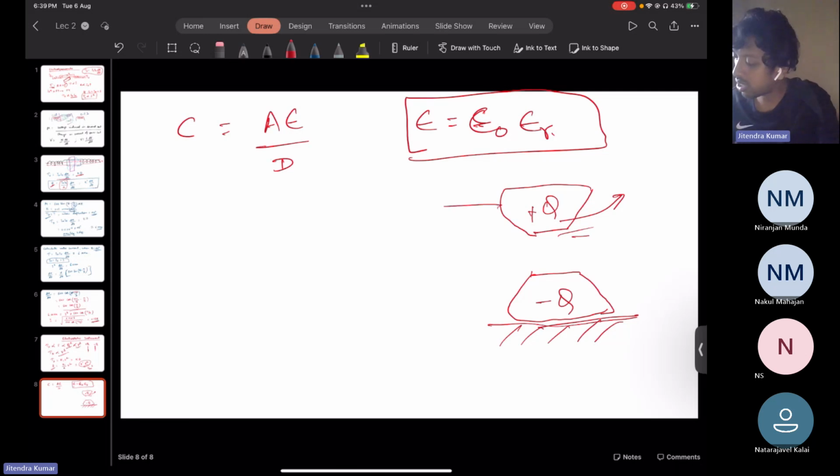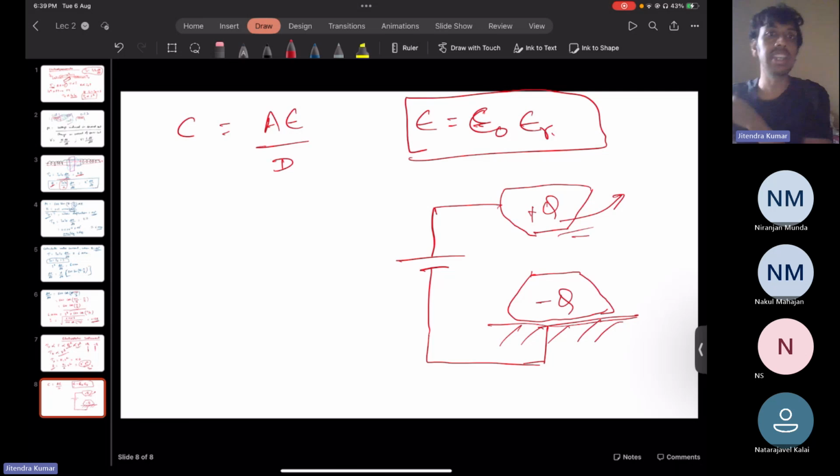Because once the voltage is applied between them, there will be force. And since in a normal circuit, both the plates are fixed so that none of the plates move. But here, intentionally, one plate is kept fixed and one is kept flexible to rotate. So one plate has to rotate because of force. Because of force, there will be some torque.